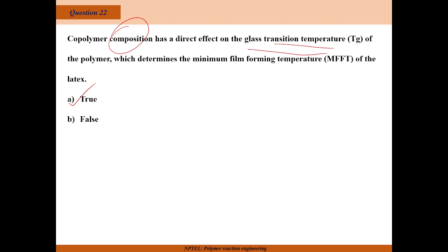The polyamic acid resin cannot be directly converted into film, but because of its high initial viscosity, you can cast it as a resin over a drum, then evaporate the solvent, and it gets deposited as a film. Whereas polyethylene is drawn or blown into film. You blow it and convert it into a film.